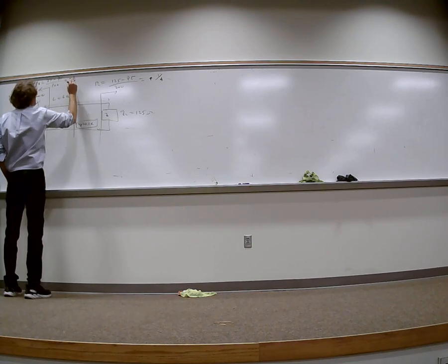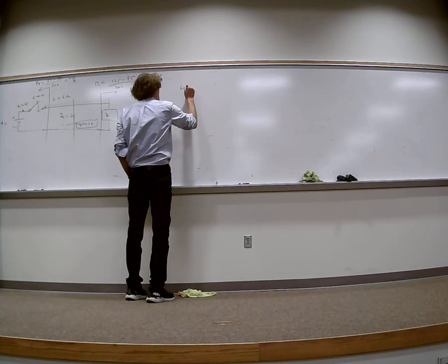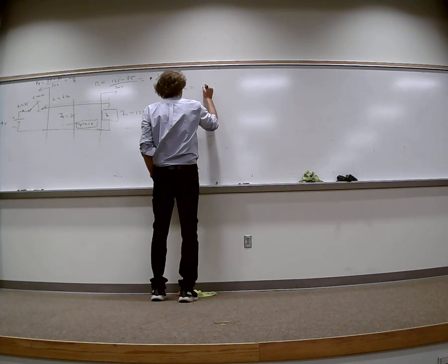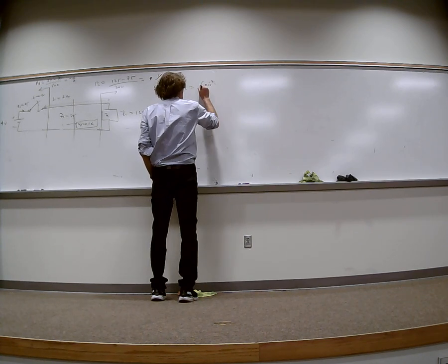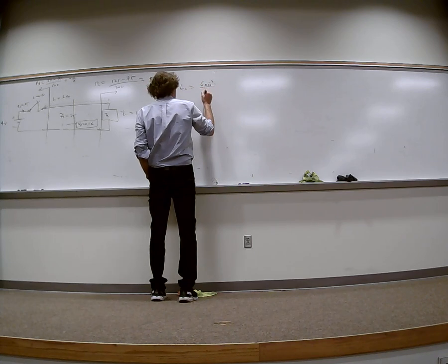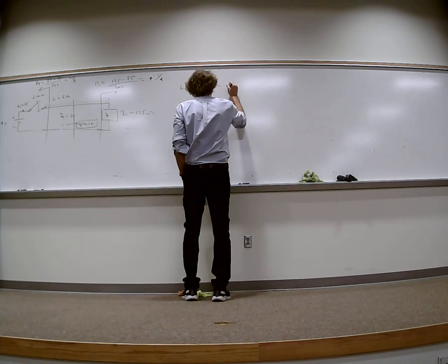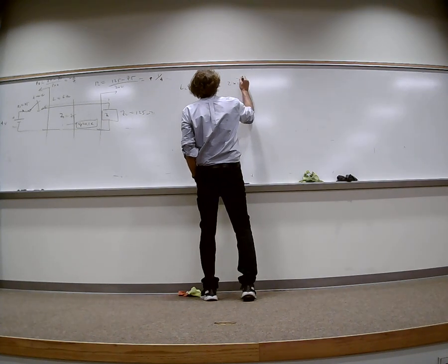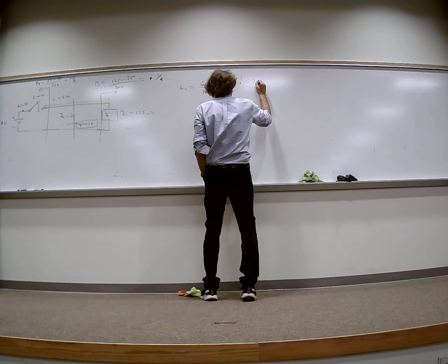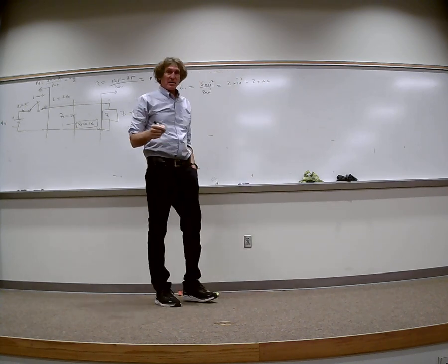Then I'm going to find the time it takes to go down the line. That's the length of the line, 6 centimeters, 6 times 10 to the minus 2, over the speed, which is 0.1 times c, or 3 times 10 to the 7th. So that's going to be 2 times 10 to the minus 9, or 2 nanoseconds, correct, class? You all with me on this?